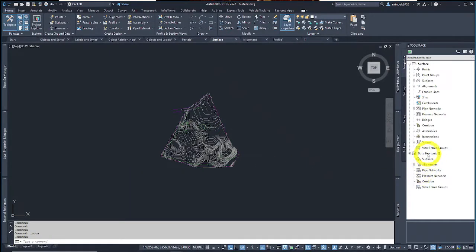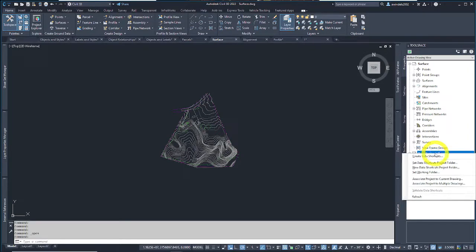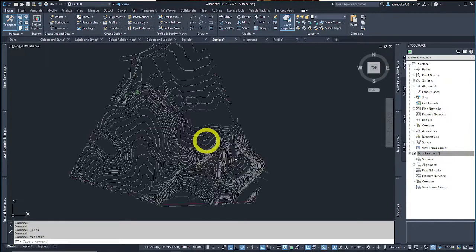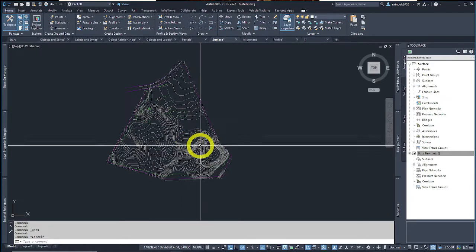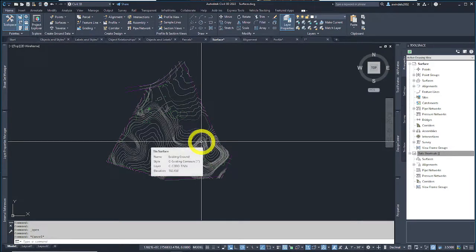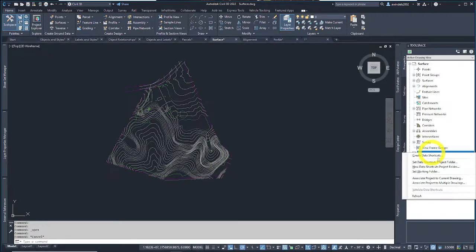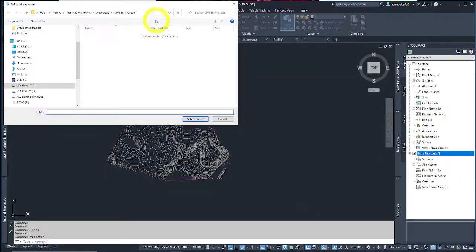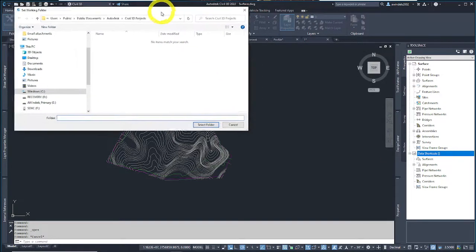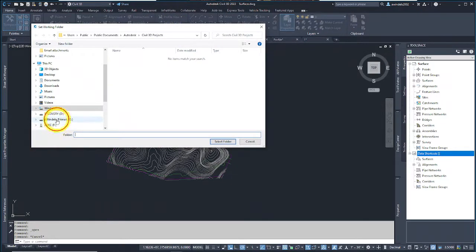let's right-click Data Shortcuts. This is our first step to establishing. A lot of times, so this is, say, my survey, my land survey of existing conditions. This is a lot of times how they start. I data shortcut in existing conditions into other maps to use existing conditions in multiple design files. This would be a good, typical starting point, really. We'll start by setting the working folder. So one more time, right click, not left click, set the working folder. It wants us to set it, browse to our chapter files. So wherever you save those, bear with me for a second.